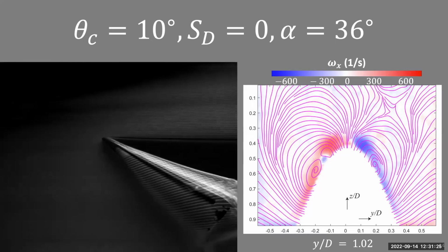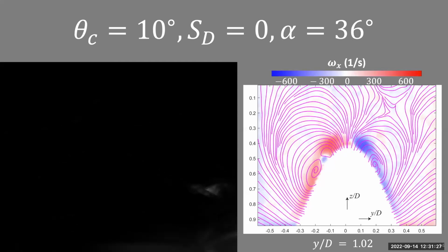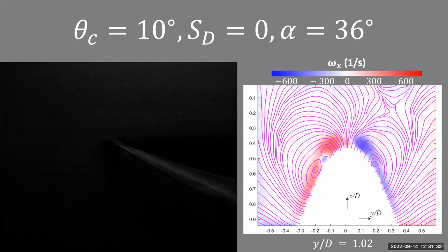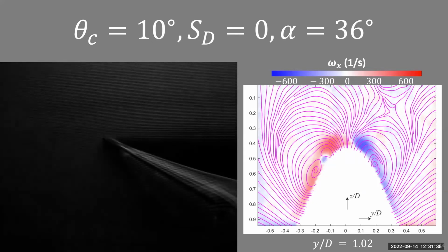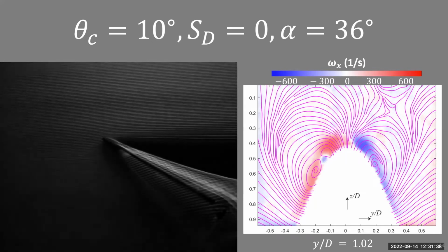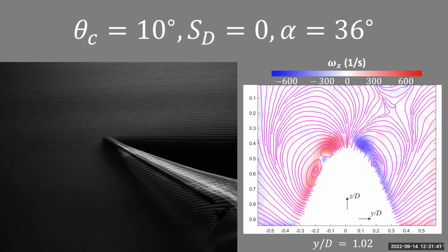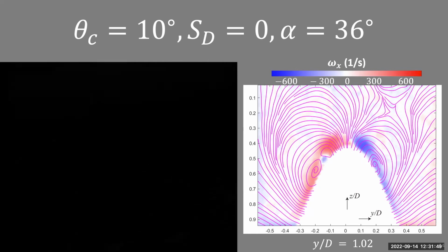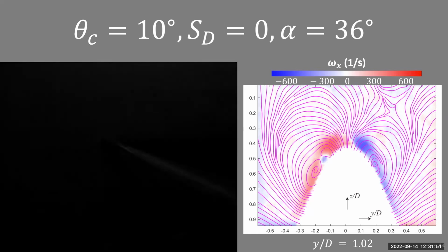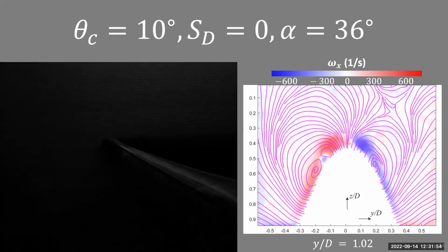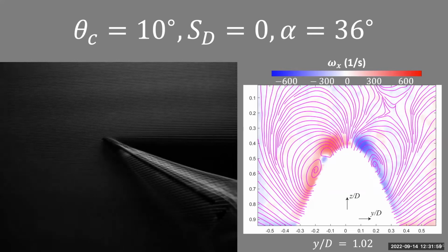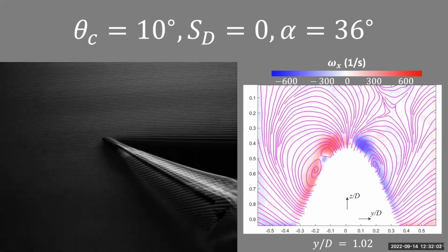One thing to note that we see here is there's symmetry in the actual scaling of the vorticity on both sides of the Z plane. Furthermore, we see that there are these primary vortices, secondary vortices, and tertiary vortices. So three vortices are forming on each side. There's a slight asymmetry in the setup. This could be a result of slight offset of the actual measurement planes and potentially some asymmetry in the upstream flows. However, as we get further along the length of the cone, the local flows overcome these asymmetries, as we'll see in the future.